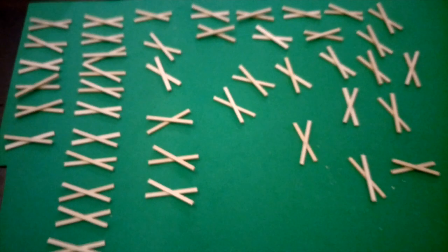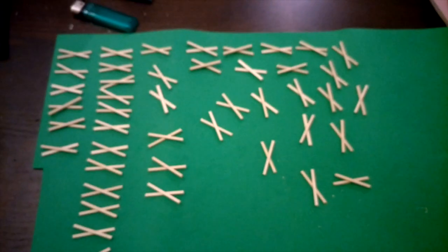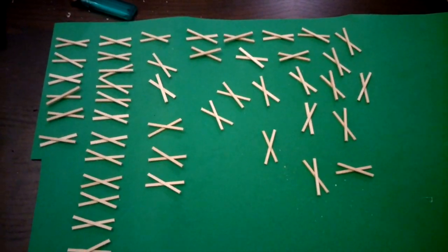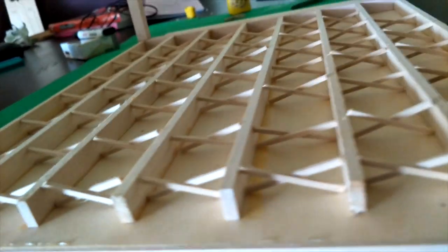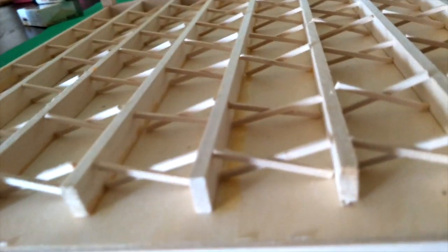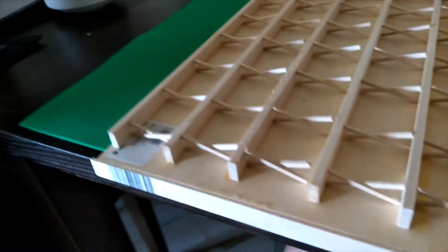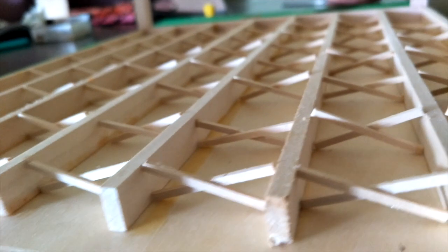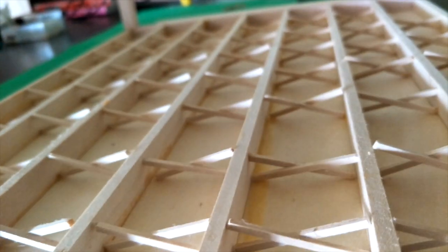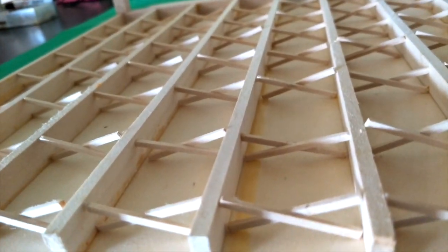For timber upper floor, there are two methods in installing the struts. It's either solid blocking or herringbones. Herringbone struts should be at least 38 by 38 millimeters. On the working model, we are using basswood strip to create the herringbone struts. The basswood strip was cut into small pieces and glued between the floor joists.